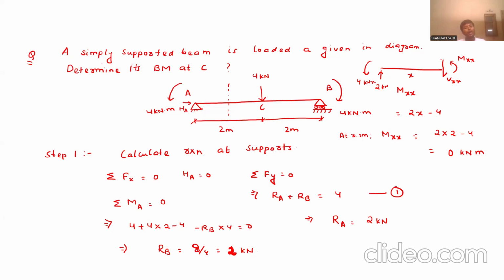Please write down the solution and let me know if there is any issue you are facing. Can you people draw the bending moment diagram for this question? Now check, if the beam and the loading are symmetrical, your bending moment will also come to be symmetrical.